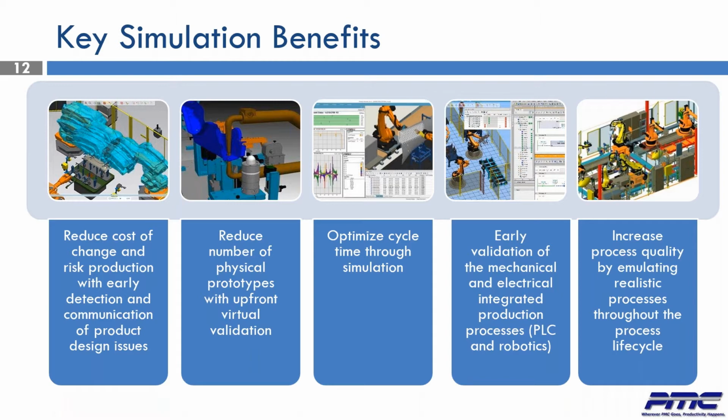We can, for example, create a new trajectory already inside the simulation environment, or in some cases, we can download the real robot program from the robot, upload it to the virtual environment, and rework its trajectory there. This brings us more flexibility, more speed in the changes, and avoids possible problems in the real environment. In addition, focusing a little on virtual commissioning, we are able to validate the functioning of mechanical devices through the creation of kinematics, and also validate the PLC logic and robot logic within the virtual environment. With all this, we obtain improvements in the production process and increase the quality of the process through the entire life cycle of the product.